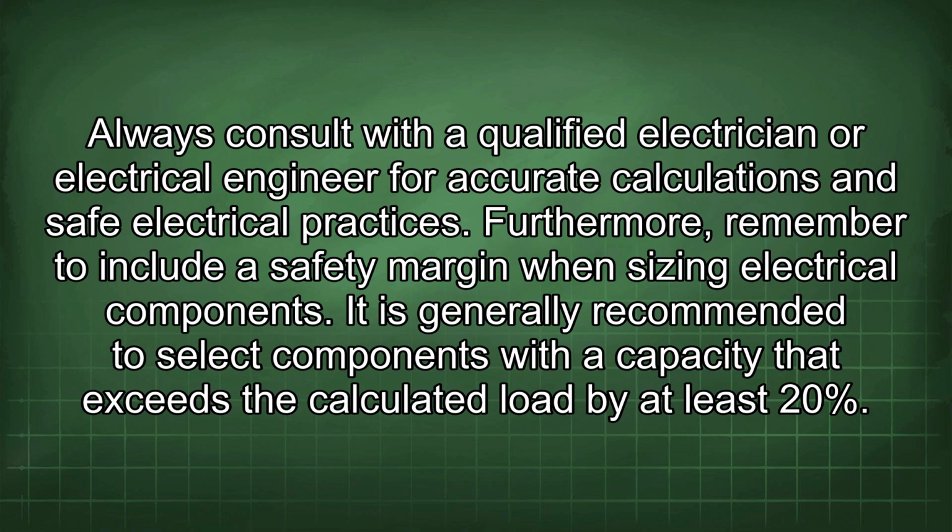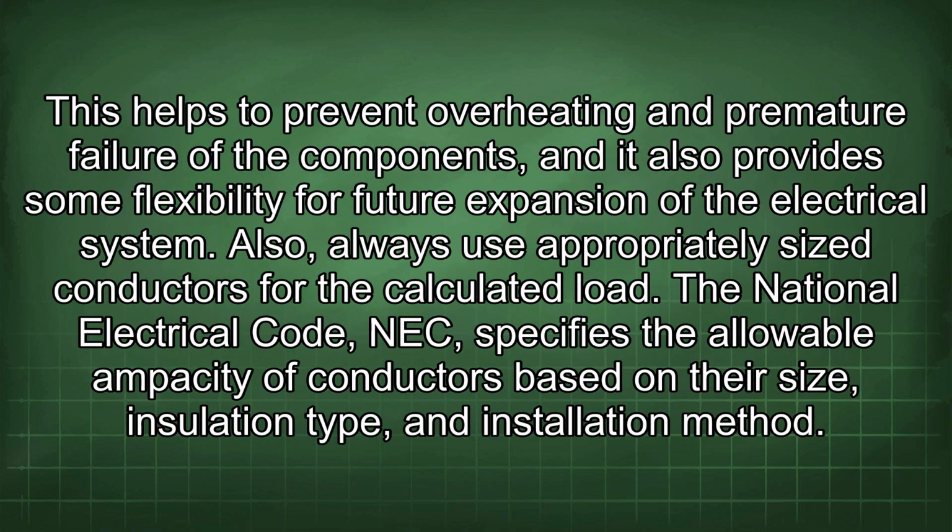Furthermore, remember to include a safety margin when sizing electrical components. It is generally recommended to select components with a capacity that exceeds the calculated load by at least 20%. This helps to prevent overheating and premature failure of the components, and it also provides some flexibility for future expansion of the electrical system. Also, always use appropriately sized conductors for the calculated load.